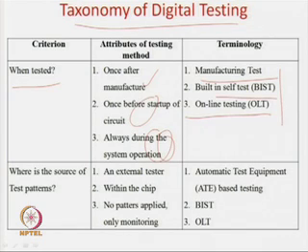Now, the question can be asked, who applies the test patterns, like we have seen for the NAND gate, 0 0, 0 1, 1 0 and 1 1. Who is applying these test patterns? If it is a manufacturing test, like the ATE example I have shown you, that is the equipment. If the equipment applies the test pattern, we call it ATE based testing. Like now in a BIST, so what is a BIST? BIST is built-in self-test. In this case, the circuit is starting its operation, but before that we apply some test patterns and get a response.